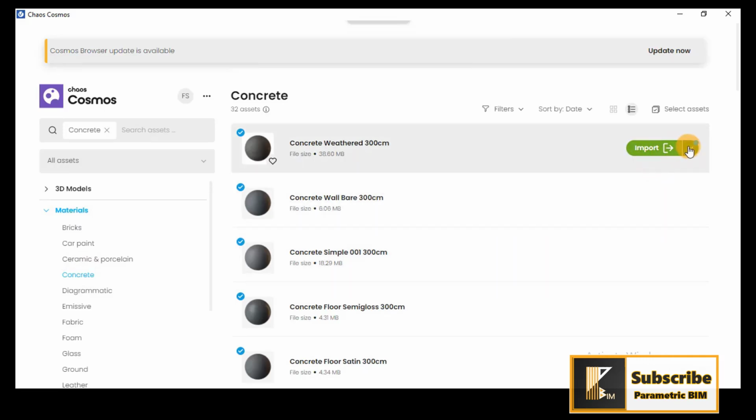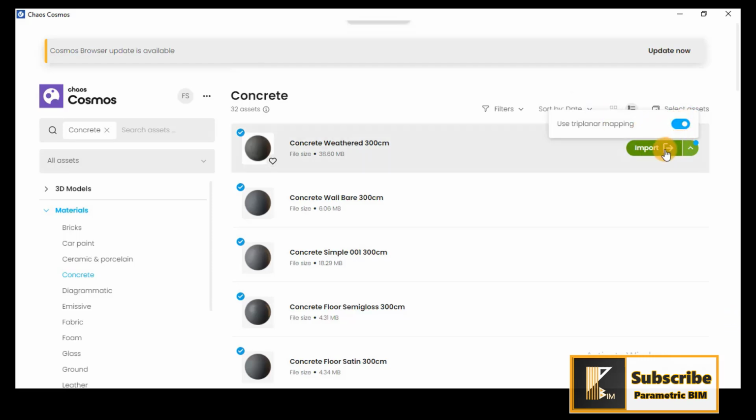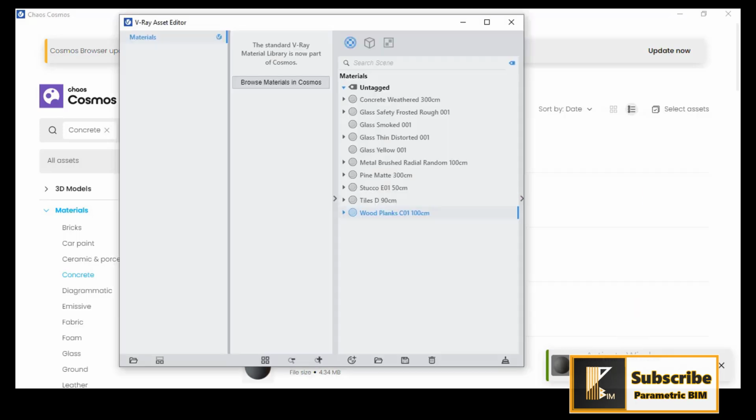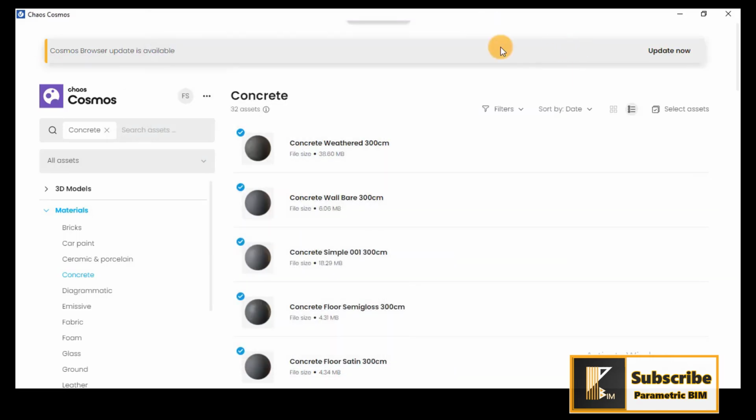Once it is downloaded, you can click here and you have the opportunity to use the mapping, or you can click to turn it off. But if you need to map it, you can click the on button, and then you can import. Once imported, it will automatically go to the Vray asset, and the Vray asset editor will open automatically. So this is the idea behind the Chaos Cosmos.